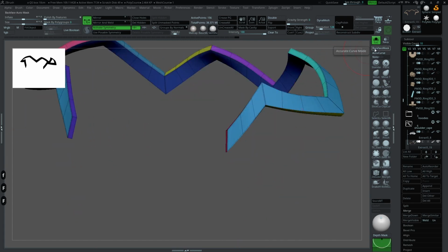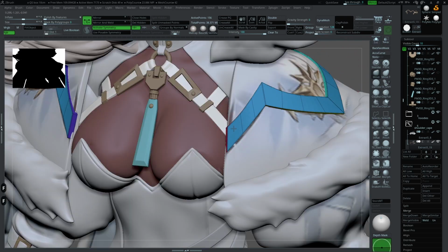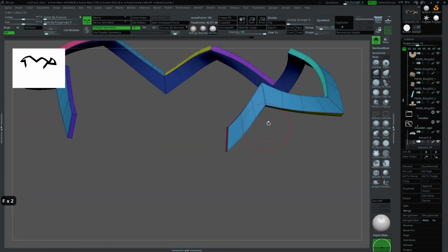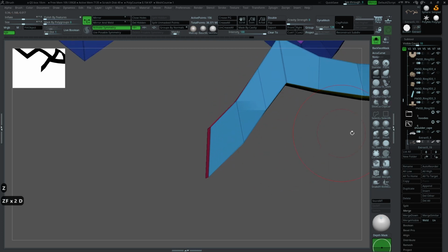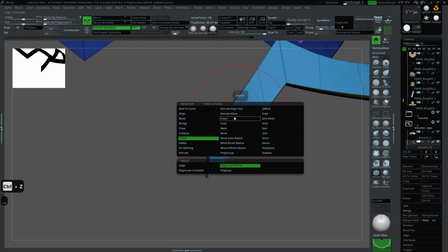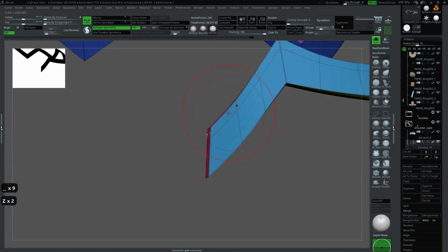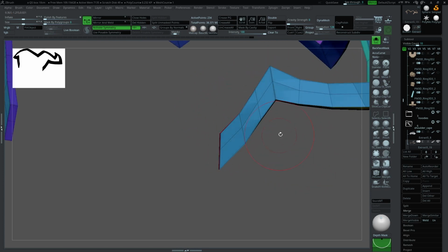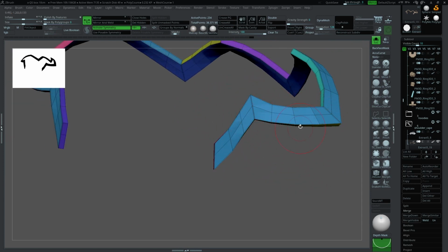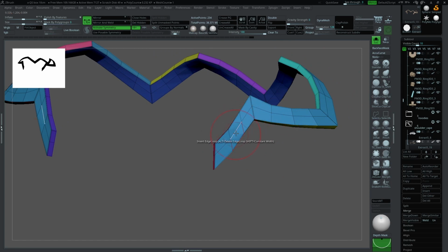Now once we finish the base shapes like this, we can add the edge line here, or we can just add using the Z modeler, insert like this, and then we add another thickness. But for me, I prefer to add it when I'm already at subdivision level. So I add another line here just to make sure we have more details on the edge line here.